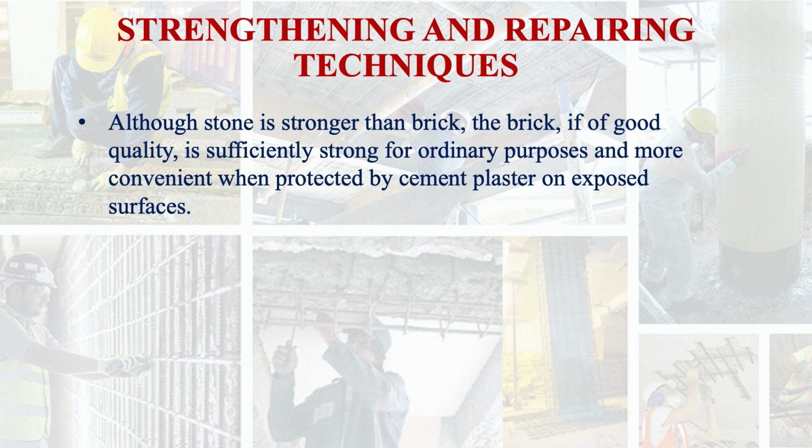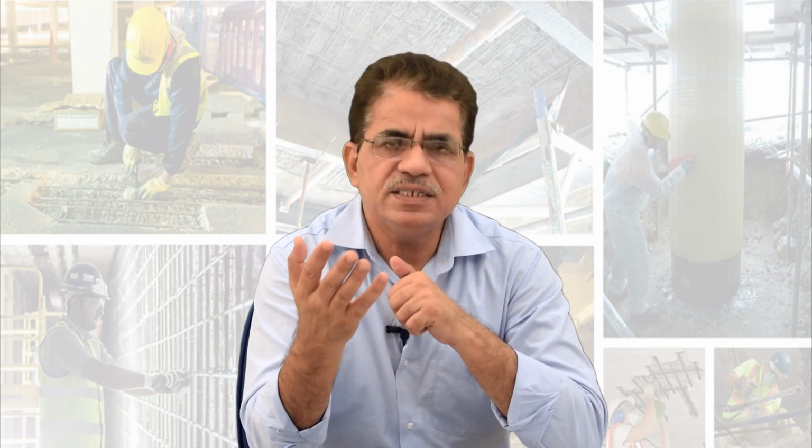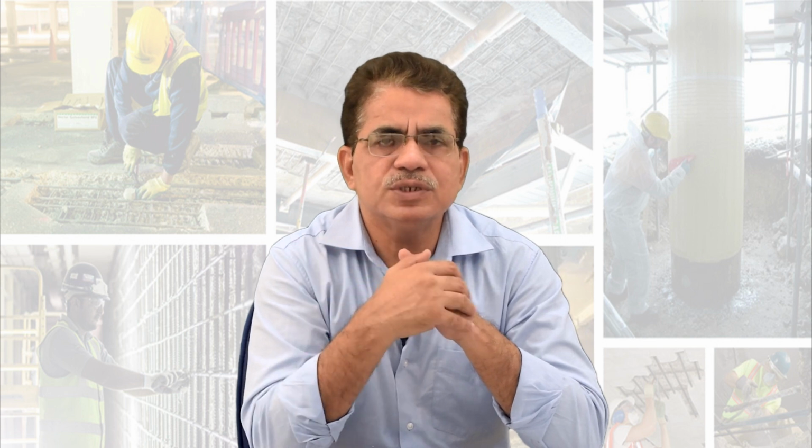Although stone is stronger than brick, the brick, if of good quality, is sufficiently strong for ordinary purposes and more convenient when protected by cement plaster on exposed surfaces, because working is easy with a brick in comparison to stone.